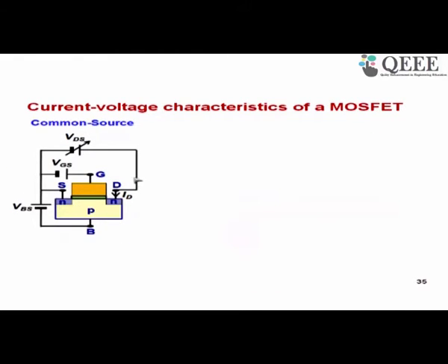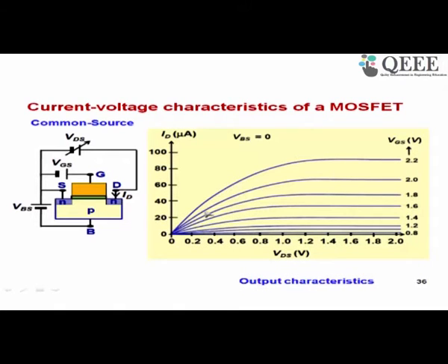Okay, come back to this transistor. This is NPN. This is an N-channel MOSFET. So here the drain current is into the drain terminal, and you have the drain to source voltage. When you vary this voltage, how does this current change? You keep your VGS constant and vary VDS. As in a bipolar transistor, here also current increases and then saturates, and as you increase your gate to source voltage, your current increases. However, some differences can be seen here from the bipolar transistor.